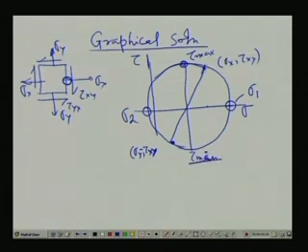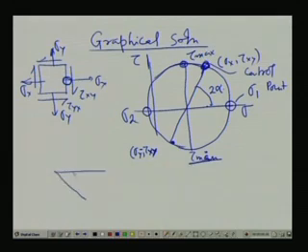What is the angle? This you always call the control point. Now, from the control point, how are we reaching this point? By say 2 alpha. So, we draw a line, come by here alpha, just make it half. Then this gives the orientation of sigma 1 as well as the value of sigma 1, you can read it from here.